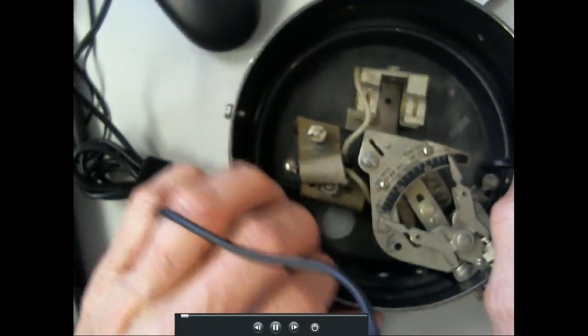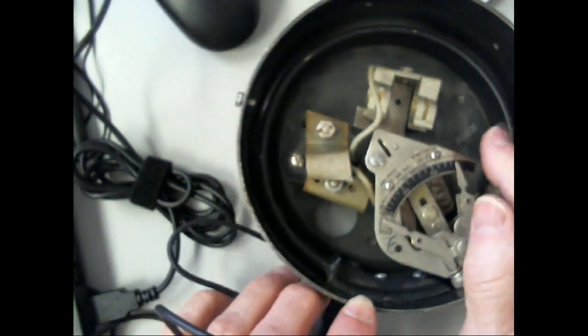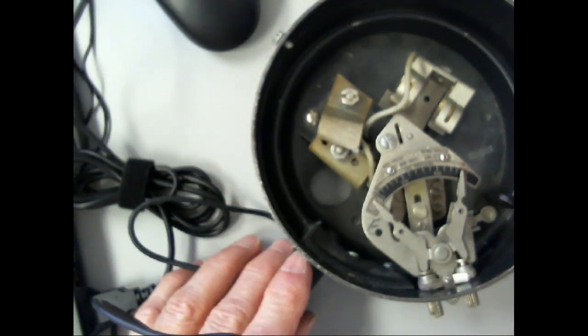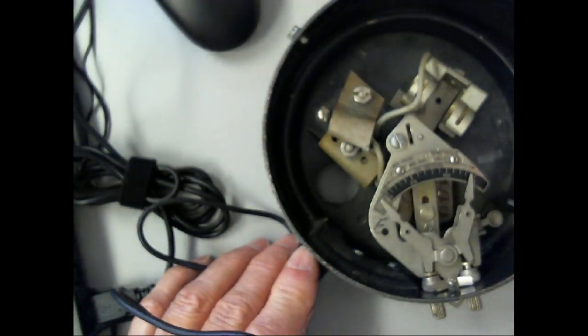This is what we call a Bourdon tube. Can y'all see it around here? Bourdon, B-O-U-R-D-O-N. So notice it's in the shape of a C and it's hollow. So when I put pressure in here, what's it going to cause the C to do? Anybody remember the party blower? Yeah, that was a Bourdon tube. So it's in a circle, right? And when you blow on it, what did it do? It wanted to open up. And that's all a Bourdon tube is.